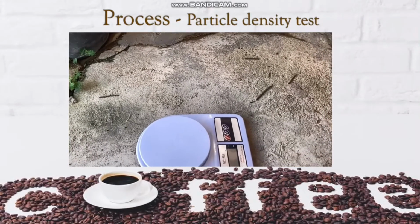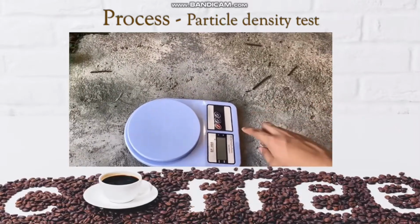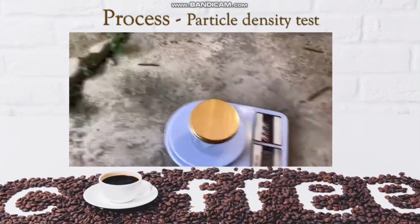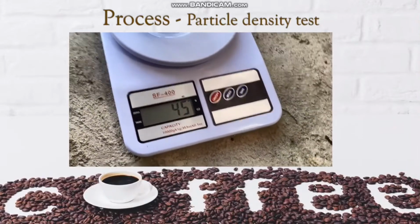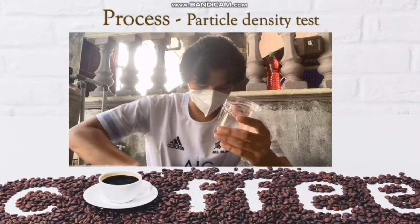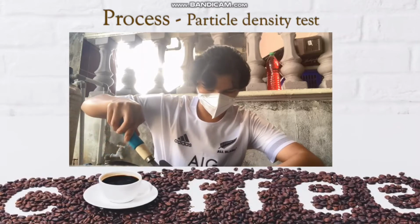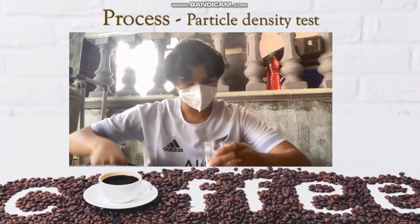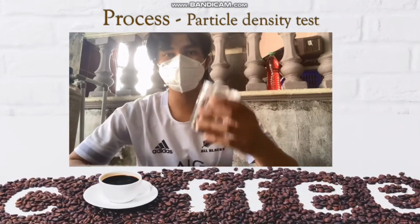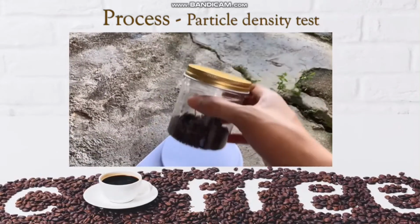For the particle density test, now we will measure the weight of an empty glass container. It is 45 grams. Next, we will fill the jar with the soil sample. Next, we will weigh the soil sample with the jar container.